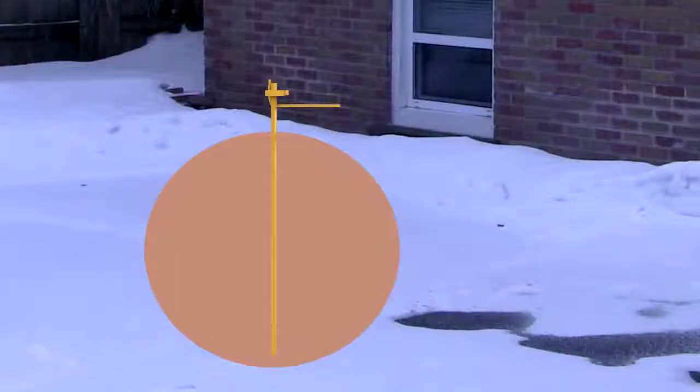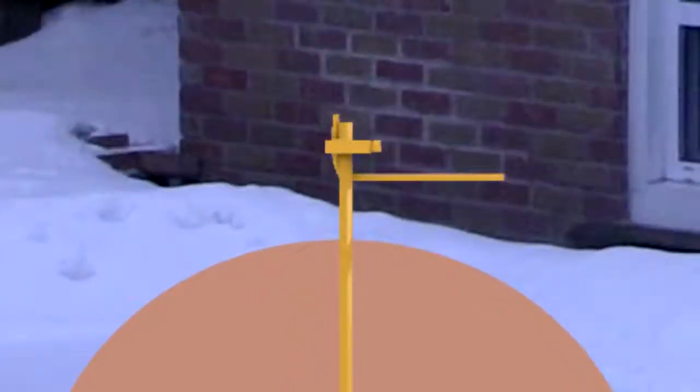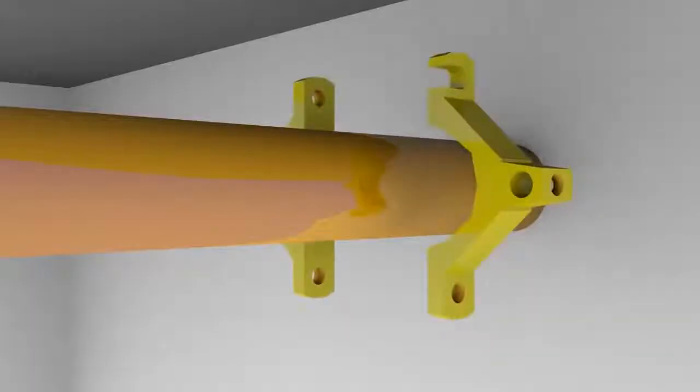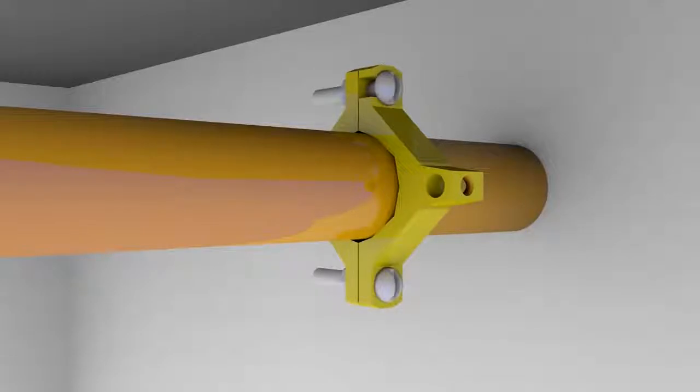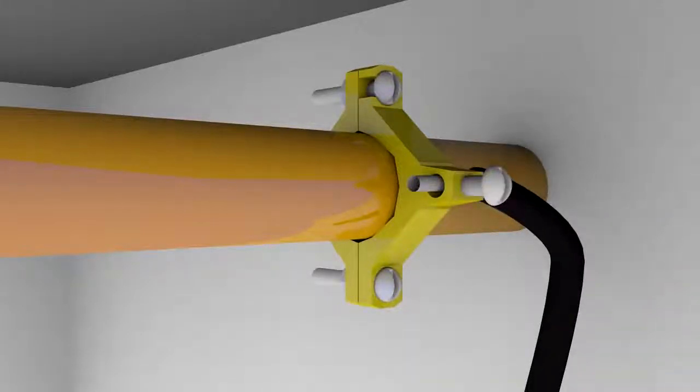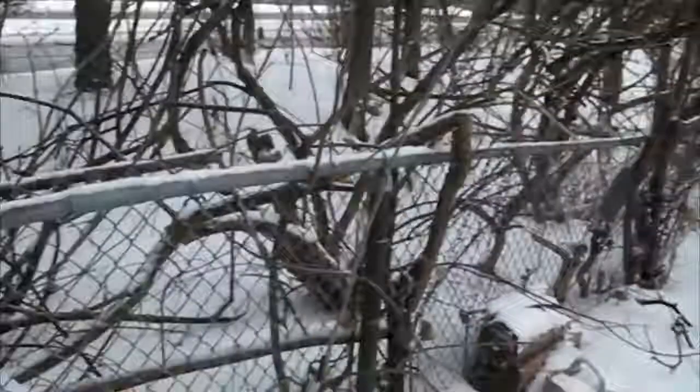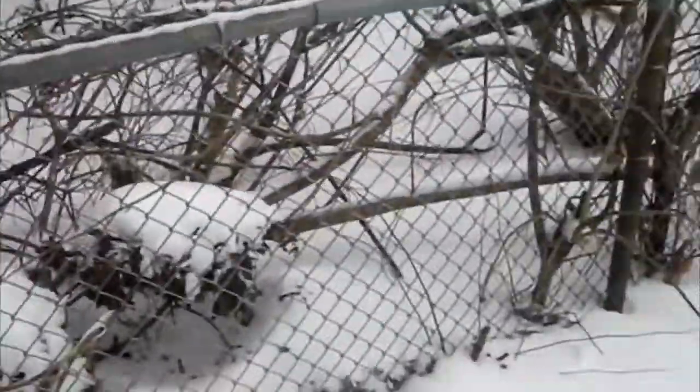A fairly safe way to ground that, if you don't have a ground rod that you can connect to directly, is to find a metal pipe that you're certain goes into the ground, like this copper cold water intake pipe from the city. Or this metal fence would do, since it makes plenty of contact with the ground.